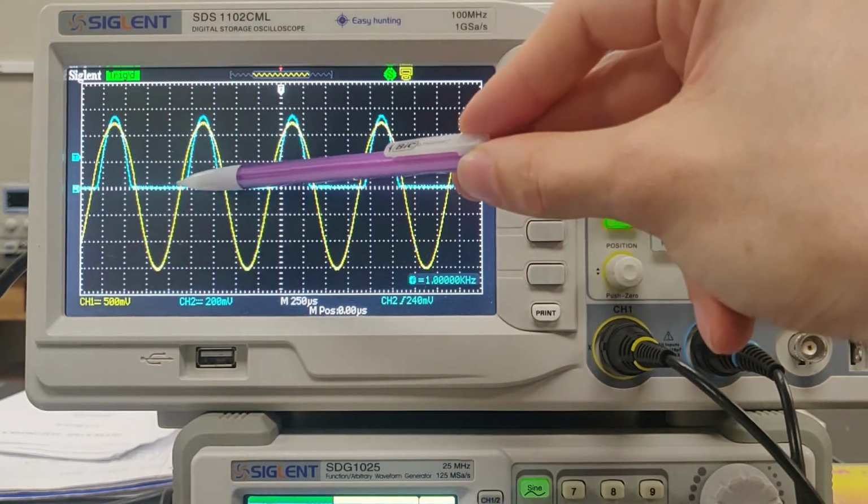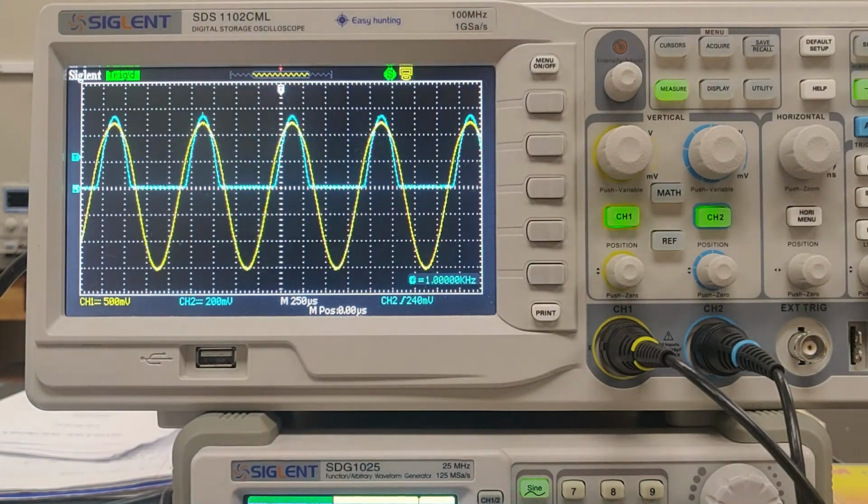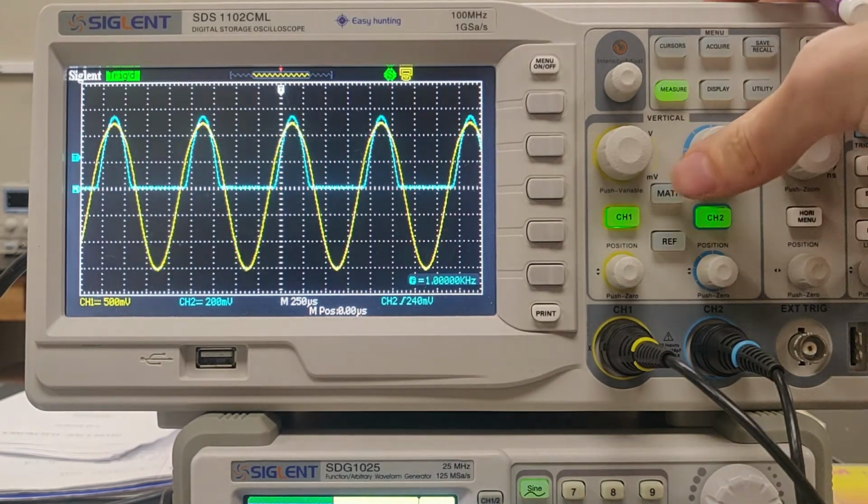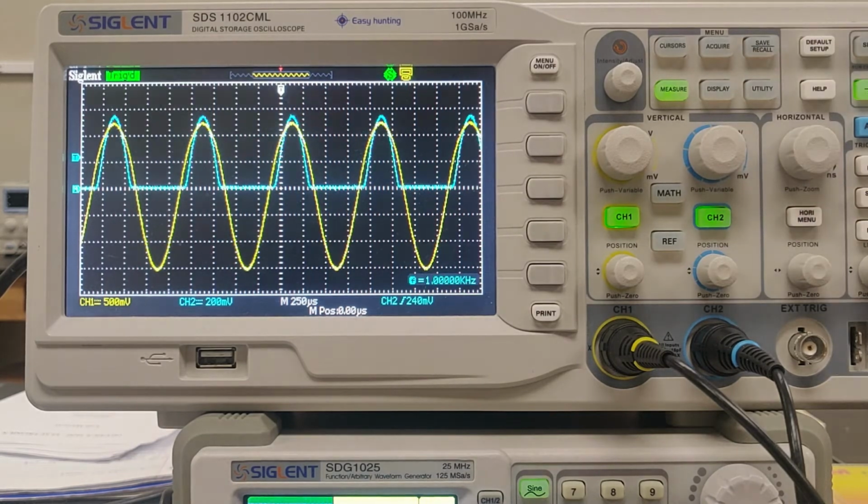So we can think about this as whenever we're in this top half of our waveform, when the circuit is experiencing this positive voltage, well, that's in the forward bias orientation, so it allows the current to flow. And then once it is being switched, it's going in the reverse bias orientation, and our voltage output from our function generator is not enough to really bypass that diode. And even if it did, since it's a signal diode, it would break down because of it. So it allows the positive half of the signal through, and doesn't allow the negative half of the signal.